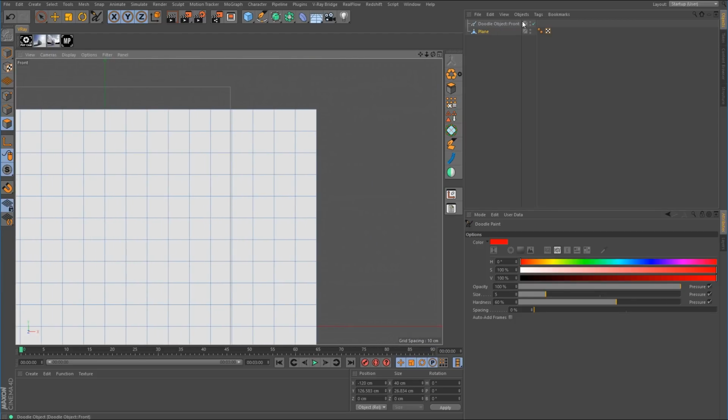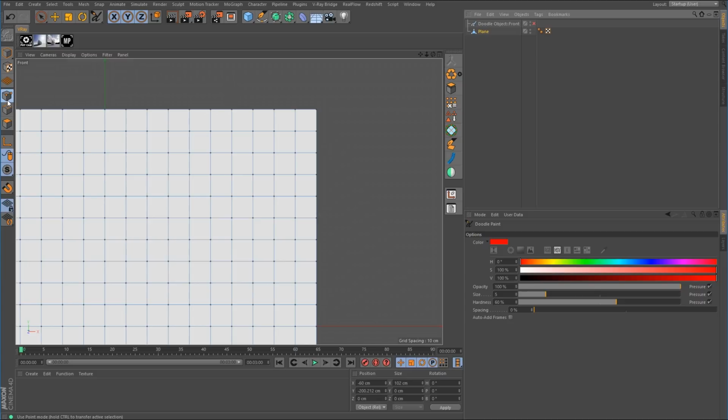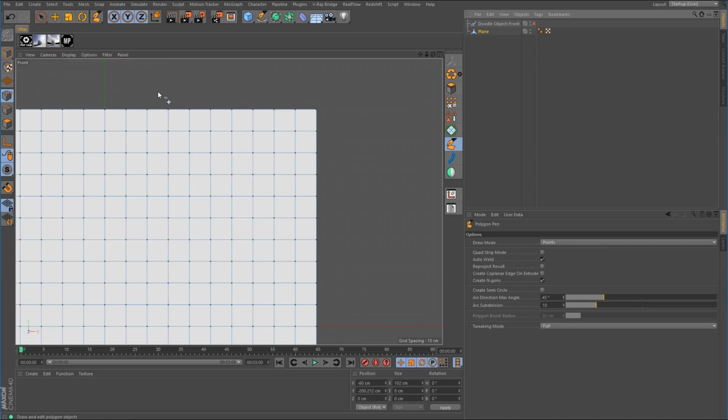Let's go up here to this corner. And another way that we can do this, let's say we want this edge to come down here and then go this way. So we can take these 3 points here on the face where this edge flow is going to go, because we want the edge flow to come down, and then right here in the middle of this face we want to take a 90-degree turn and go over to the right hand side. So this is the face here where it's going to happen. So these three outer points, we just want to weld those together into one.